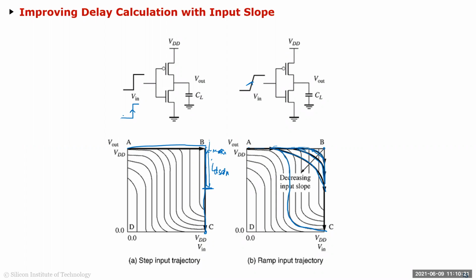We took a technology and said typically the length is always minimum. So you calculate per unit width for unit length cap, for example 2 femtofarad per micrometer, the CG. From there on, whatever is the size of your WP, WN, you just keep multiplying and adding them together, and that's your total capacitance, right? So that was your capacitance.